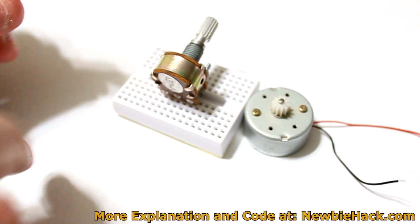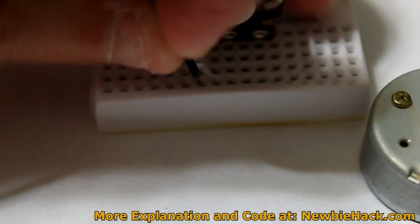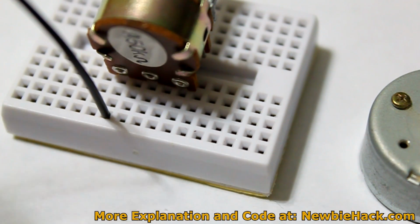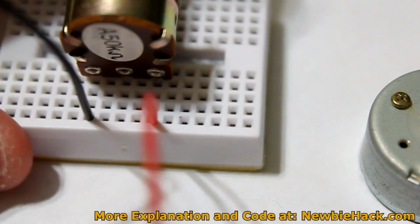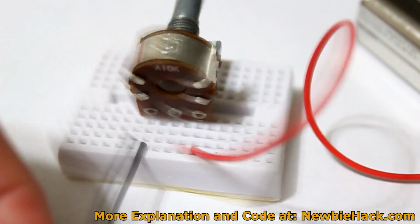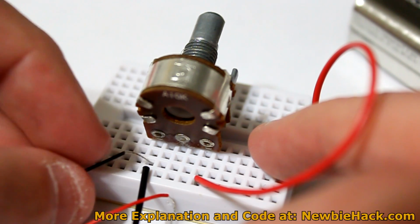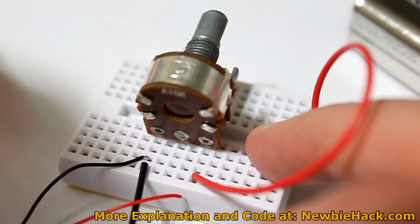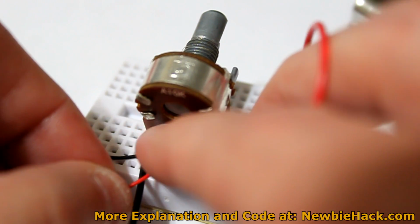I'll put the negative on one of the outer leads of the potentiometer, and the other pole to the other outer lead of the potentiometer. And what we'll get is a voltage divider constantly being changed as we turn the potentiometer, going from 0 volts to 9 volts. Now I'll plug in the two leads of the motor. I'm going to put the black to this outer lead of the potentiometer. Then I'll take the red one and put it in the middle lead of the potentiometer.